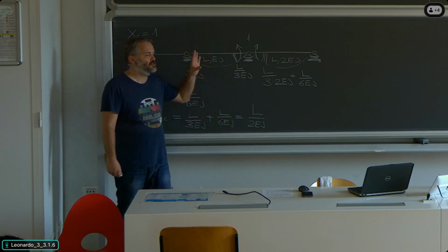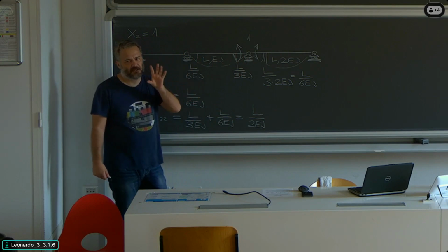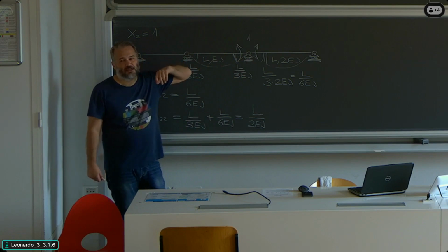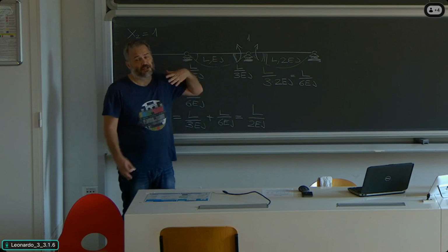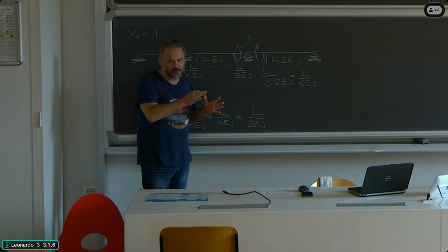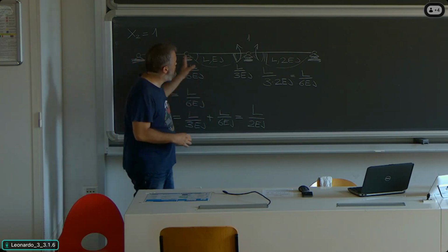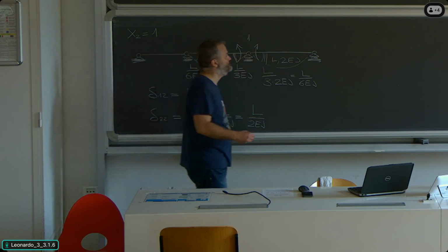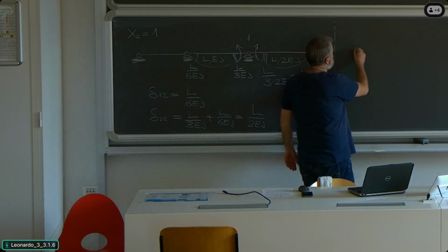Don't focus so much on the symbols, rather on the meaning, okay? Again, the standard coefficients are there just to give you an indication, for example, as regards the rotation. Span divided by 3 or divided by 6 multiplied by the bending stiffness. Then the bending stiffness, for example, in this case, can vary from one span to the other. What happens with the distributed load?